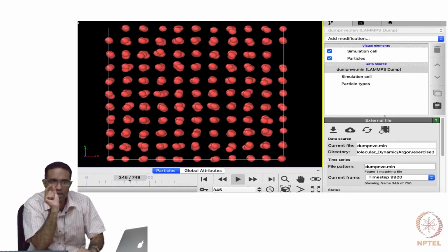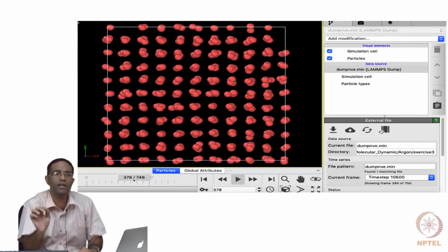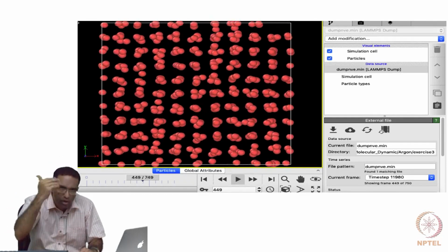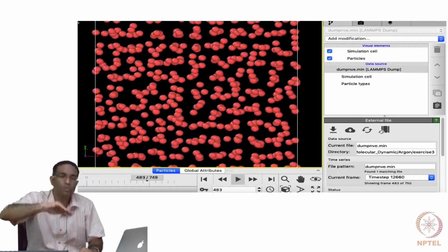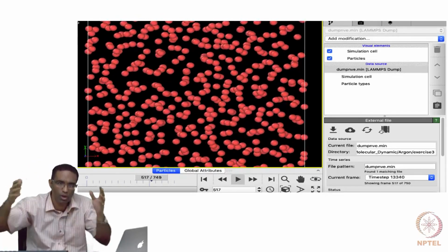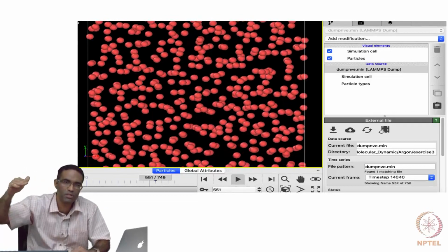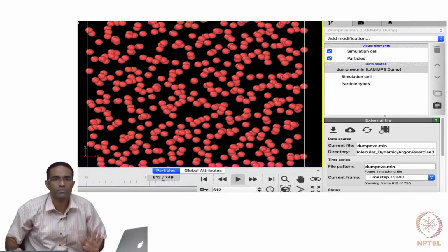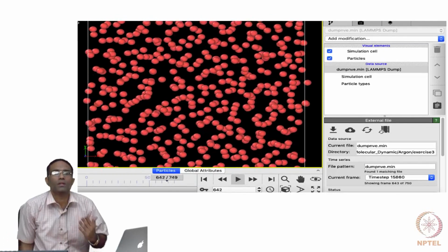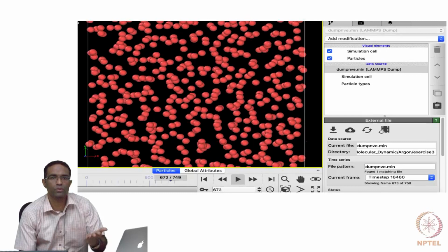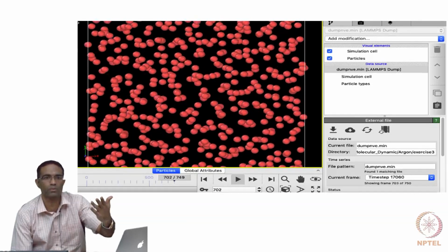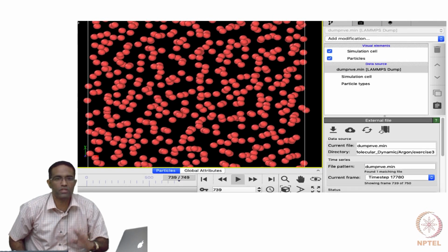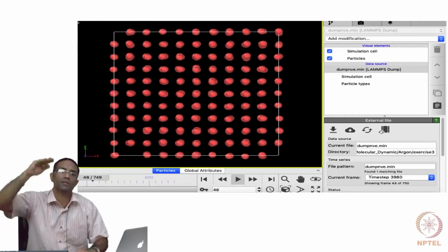So here the use of NPT is not exactly fixing the pressure or fixing the temperature. It involves changing the pressure and changing the temperature to some fixed value. Hopefully, if you have done it for a long enough time, your pressure and temperature will reach the value that you have requested. So the final values specified are the ones where I want it to equilibrate. Where you want the system to equilibrate to. And in NVT simulation, N and V are fixed. Fixed. But I want the T to equilibrate at that value.